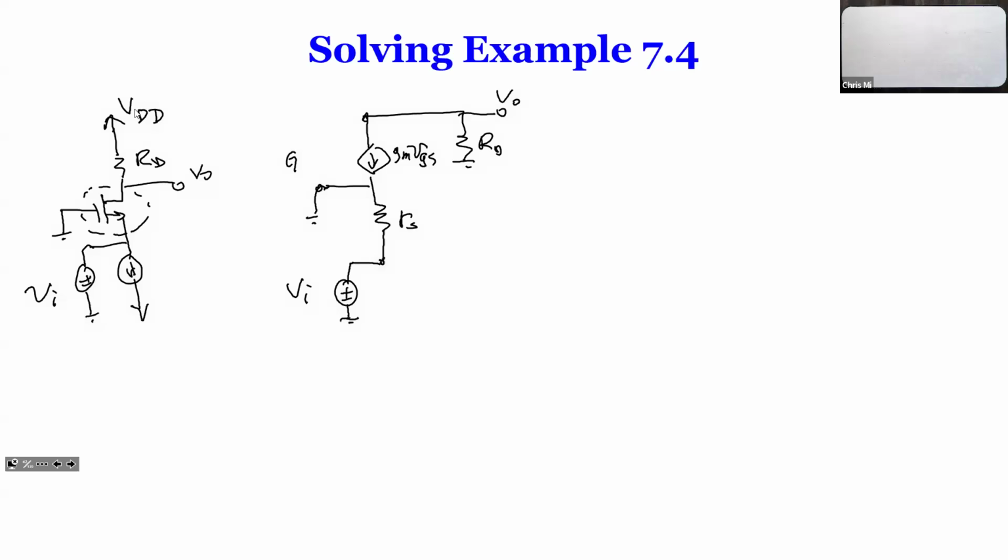Now you get quite a nice circuit. At the bottom, you don't have to change the direction right over here, since this is down here anyway. So I'm just going to draw the input over here. So where is our VGS? First of all, what I was asking is where do you mark your VGS? Across the resistor. Yes, it's across the resistor RS.